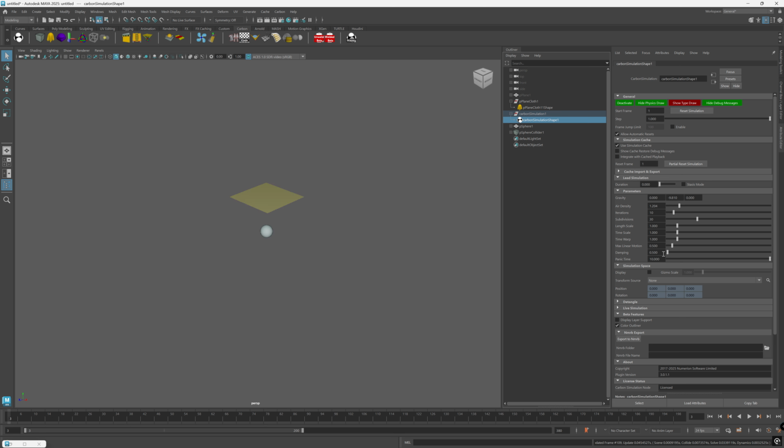Obviously, if I take this way too far up, let's say to 100, you're going to see a heavy impact like this, but you wouldn't use it this heavily. Generally, 0.1, 0.2, 0.5 are fine. The one thing to keep in mind is that it affects all objects in the scene, so all of your cloths or rigid bodies will be damped equally. This is often not what you want. You normally want to control the behavior of each object separately.